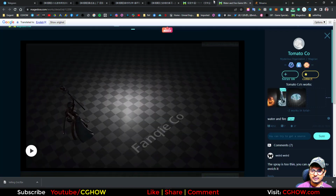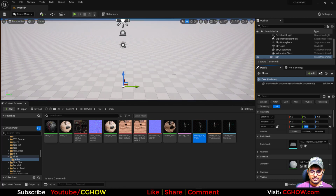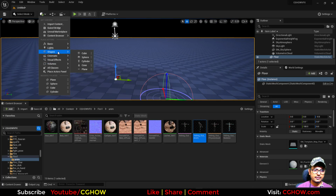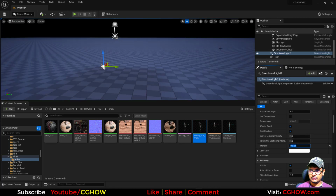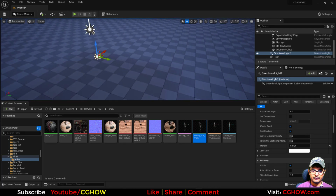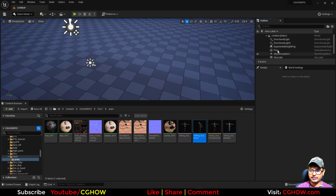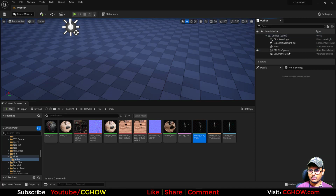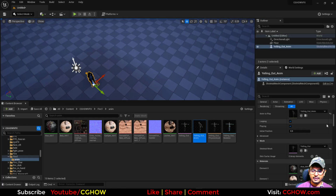Kind of this dark level I will create. So I will make that maybe 100. Then Control L to make the lighting darker. And actually I will take one more directional light. In this case, you can delete this whole thing. We just need the ground and one light. That's it. We don't need all these things. Just one light. And then I'll drag this animation to the viewport.